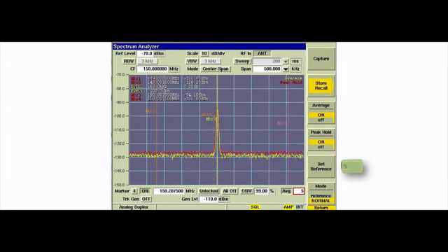We can also monitor our spectrum over time. We can turn the peak hold function on and the average mode if desired. Keep your eye on marker 2 as it is monitoring our interfering signal. Markers are displaying the peak indication of the signal, so if the signal is only up momentarily, we will still have a relative level that the signal achieved.